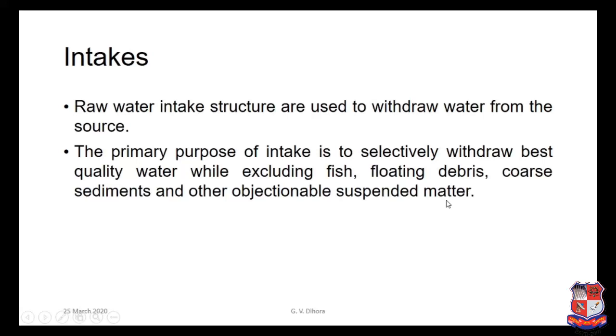Intake should be provided where the quality of water is good and water is available in all seasons, and we have to see that no floating or objectionable material enters the intake. That's why we provide a screen in the intake itself. So in a water treatment plant or water supply scheme, the screens are provided at the intake itself.